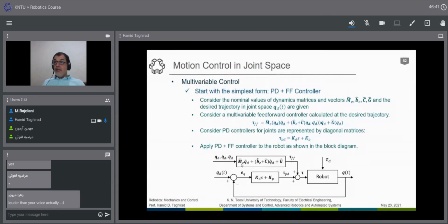And we don't use a feedback here because it's a feed-forward. We use the same Q_d, the desired trajectory that we defined before using quintic, cubic, or parabolic blend. So in the version that we talked about here, we have a trajectory planner that gives not only Q but also all its derivatives. So we know that we have Q dot.